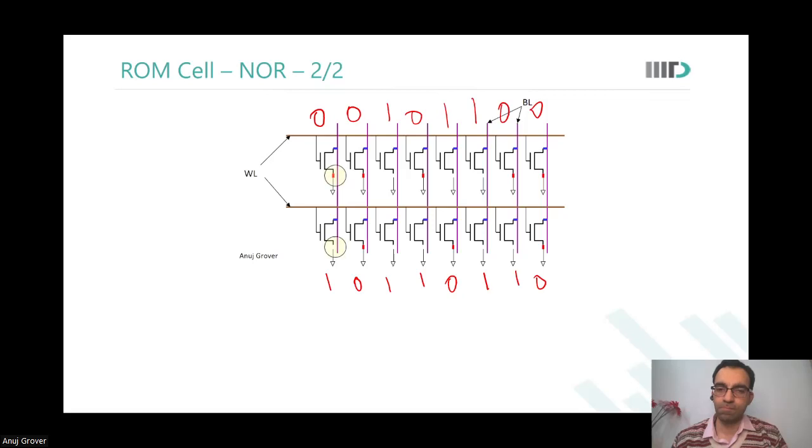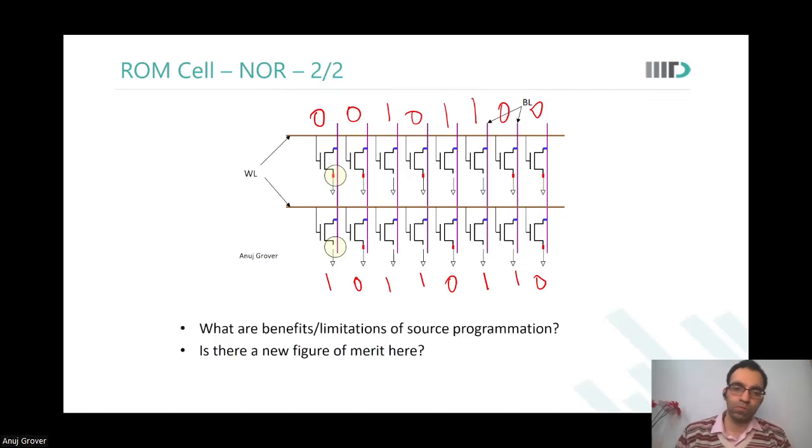Sir, in the earlier case, when we were contacting with the drain region, in that case also, with the worst case, we can basically design a circuit such that the signal will be generated only after that time. Yeah, we can do that. I agree, Raghav. But while I can design for the worst case, on silicon I want as much symmetry and as much control as is possible. With so many bit lines varying at different rates, it will be very difficult to debug if there is a failure on silicon.